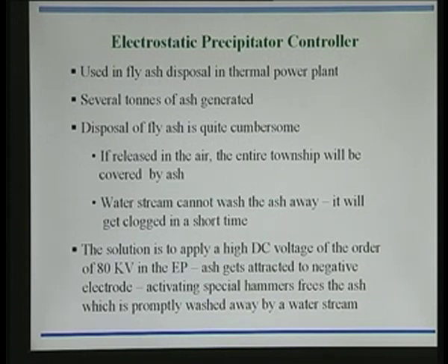Each ash particle acquires the same charge, so one particle of ash will repulse another, and they do not cling to each other. Without the application of 80 kilovolts, the ash, on the slightest excuse, gets airborne, and that is how it fills the entire township if left straight away.